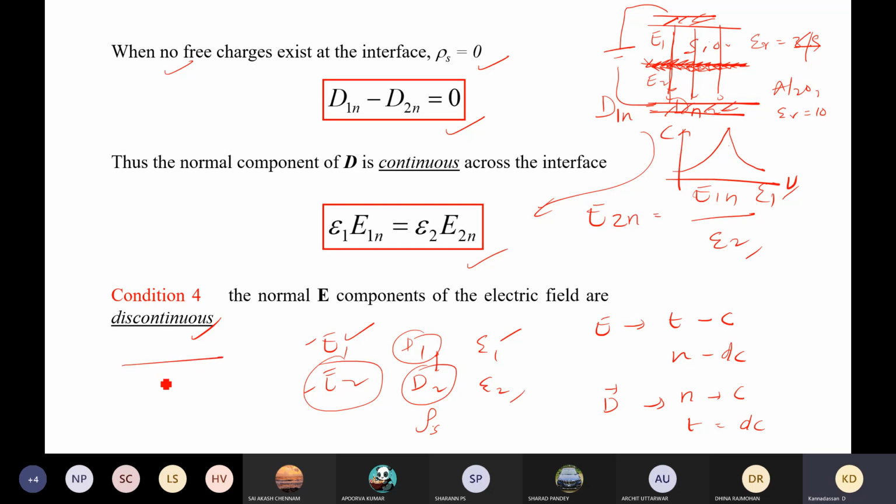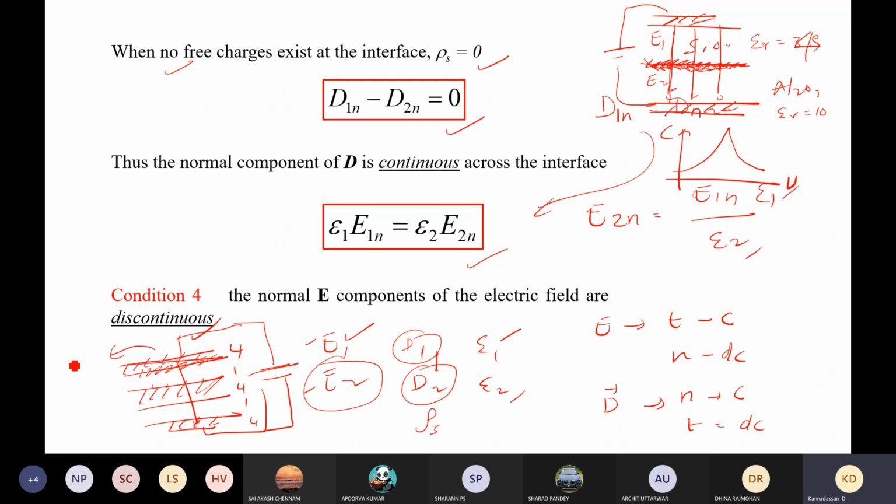So if you take a material which has very low dielectric constant, let's say I have an air medium and then silicon dioxide. So I have silicon dioxide, air medium, silicon dioxide, air medium, and then another silicon dioxide. If you keep that, it looks like these materials are having 4, 1, 4, 1, 4, 1, like that. But the moment you apply the voltage, which makes the field distribution, the charge density in the interfaces will be very high, which will result in the total effective dielectric constant sometimes going greater than 1000. So in this way, one can easily increase the dielectric constant of a particular material.